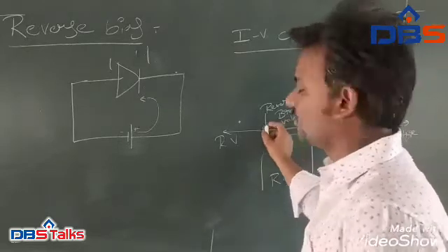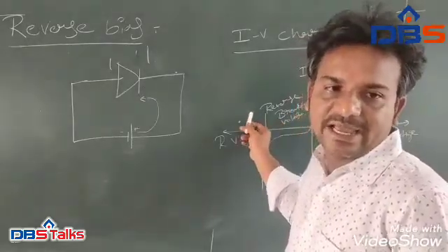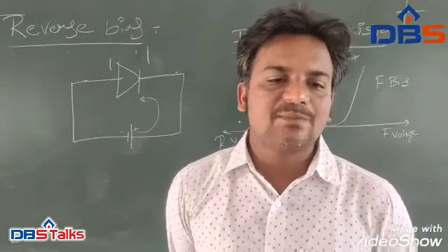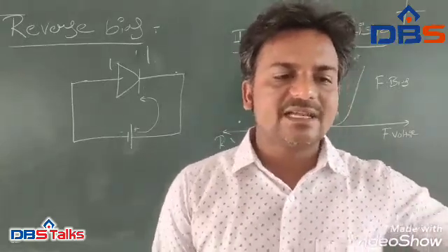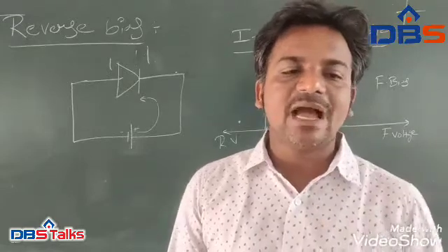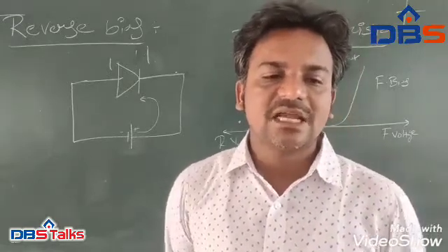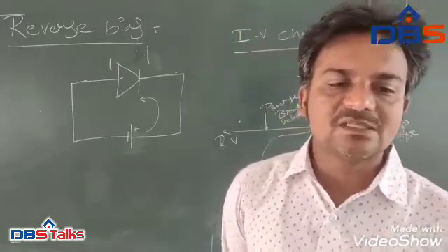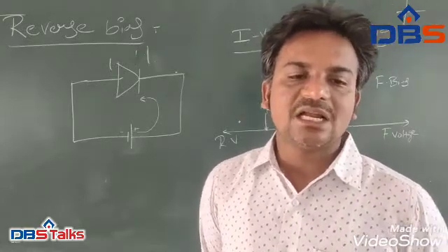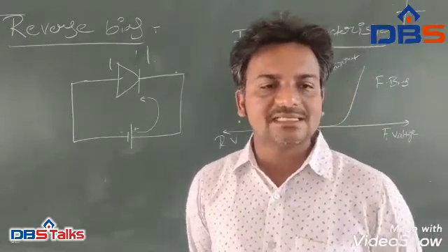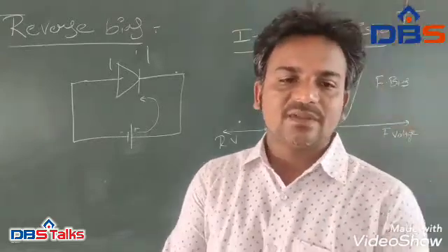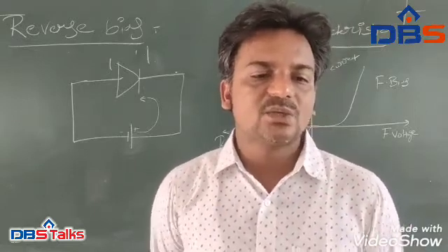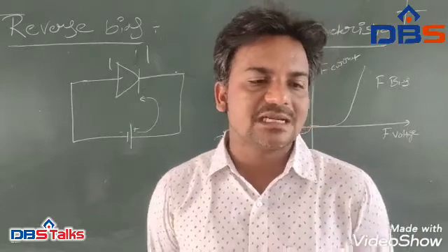That means wherever the reverse breakdown voltage exists, it will exist in this condition. When the PN junction is used as a practical device or as a rectifying device, we first need to bias the junction. That means connecting a voltage potential across it. On the voltage axis above, reverse bias refers to an external voltage potential which increases the potential barrier. An external voltage which decreases the potential barrier is said to act in the forward bias direction.